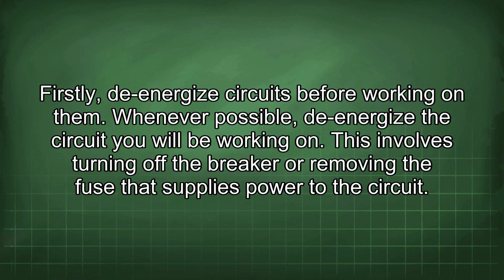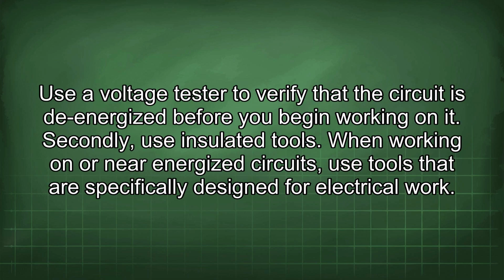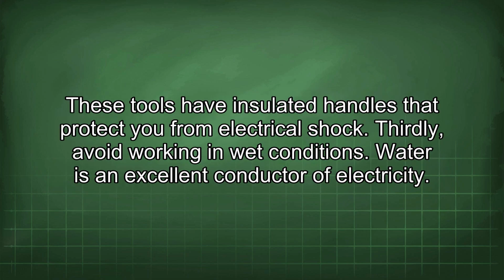This involves turning off the breaker or removing the fuse that supplies power to the circuit. Use a voltage tester to verify that the circuit is de-energized before you begin working on it. Secondly, use insulated tools. When working on or near energized circuits, use tools that are specifically designed for electrical work. These tools have insulated handles that protect you from electrical shock.